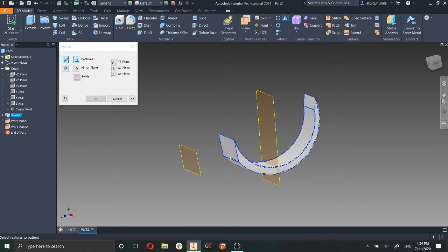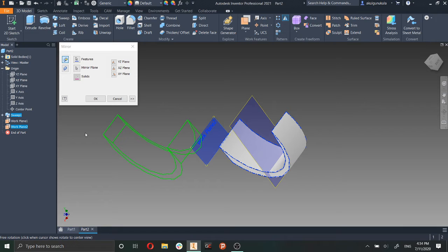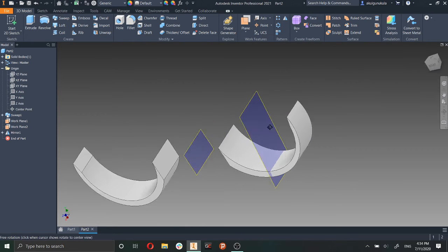In the 2D sketch, it'll be different lines, drawings, and whatnot. And then you choose a mirror face. The mirror face in the sketch would be a line that you want it to be reflected over. And this will be the work face. And you will see that this is what will be mirrored over, because that's what mirror is. And there you go, you see.